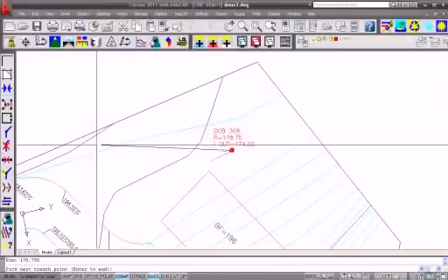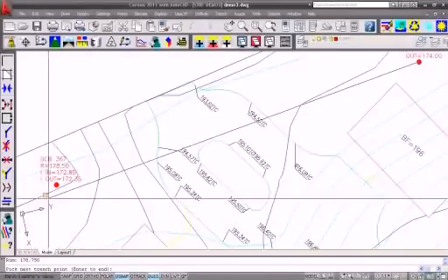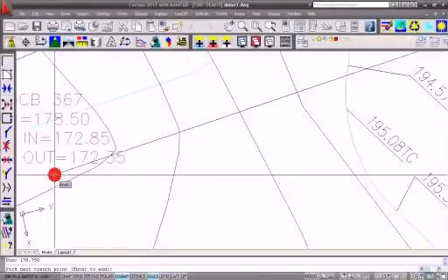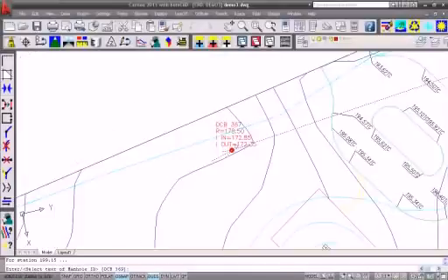So I can pick any point here on the drawing, and I want to go to my next manhole here and left click. Okay? Select text for the manhole ID. Select that value. You can see right above here it's reading that value off of the text in the drawing. This is something that would also work with that new PDF. If we converted all this text from a PDF, this command would now be able to work with it. Invert in, the invert out, and the rim elevation.